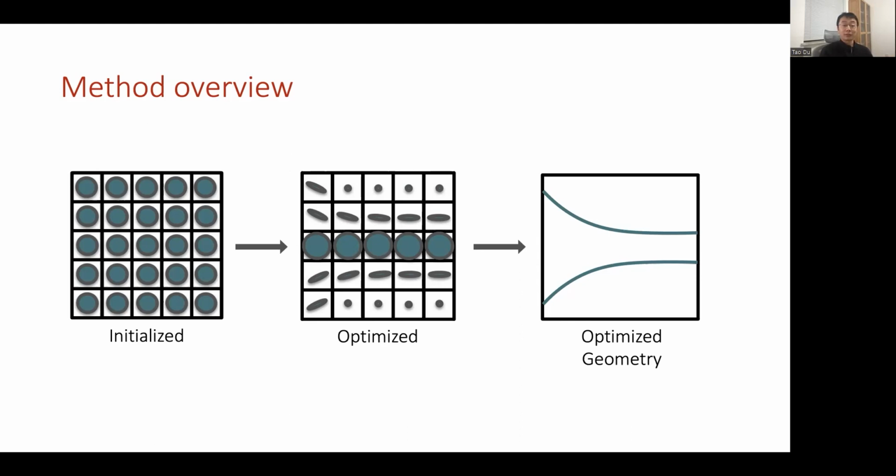And if you are familiar with topology optimization, you might recognize this pattern, as we are basically doing very similar things here. So in order to represent a microfluidic device inside this domain, we're going to assign a decision variable to each of the voxels. Specifically, we decide whether we want this voxel to be the solid part, the fluid part, or a solid fluid interface.